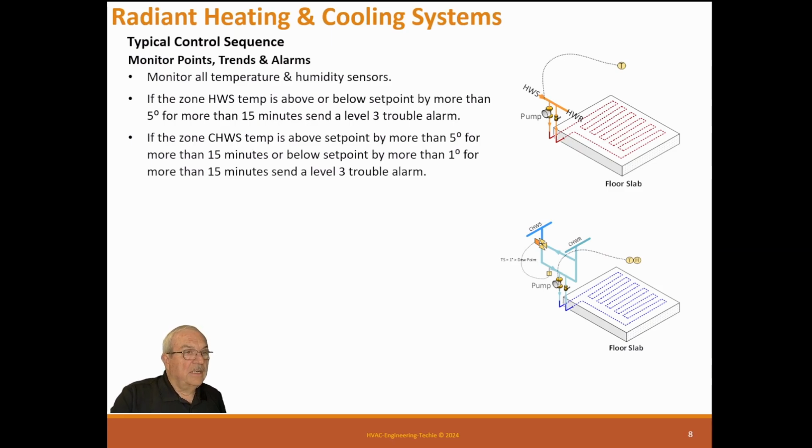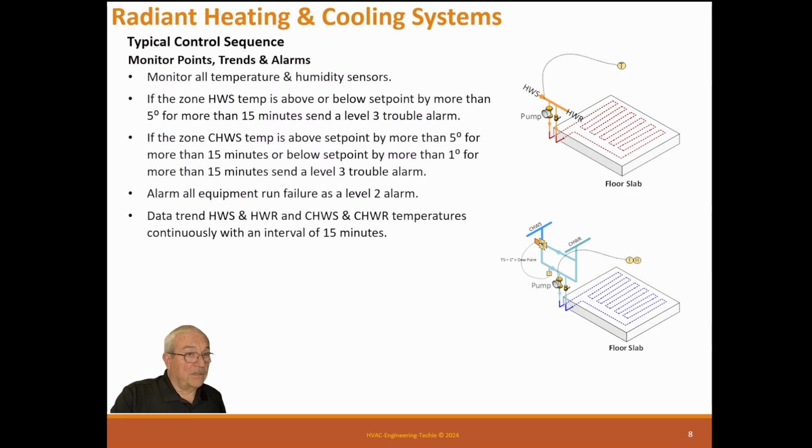Same thing. If we're out of these temperature set points, then we need to know that, but it's not super critical. Alarm all equipment run failures at level 2. So if you lose a pump, then it's a level 2. You got to get up out of the chair.